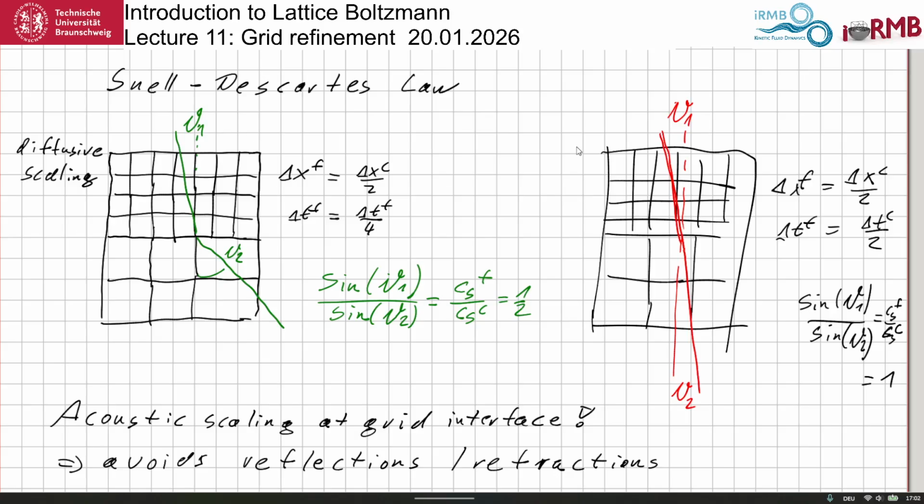When you use more finite differences, these oscillations and offsets in the second order moments, which you usually don't bother with in lattice Boltzmann, will naturally dissipate. Therefore, when you use grid refinement together with this hybridization, you don't see this problem, or you can reduce it a lot.